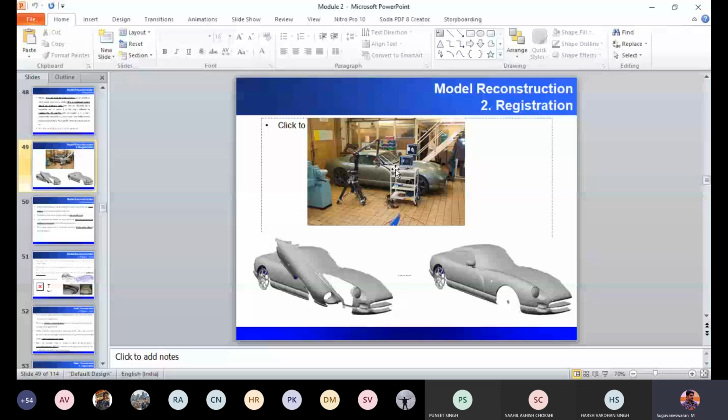For the same angle I have rotated, I have to do a rotation in the counterclockwise direction for the CAD model. When I do such a counterclockwise rotation, it will get merged with the existing part. So finally, you will get a complete 3D part. This is what data registration is: transformation of the object according to the rotations you have performed on the laser source.